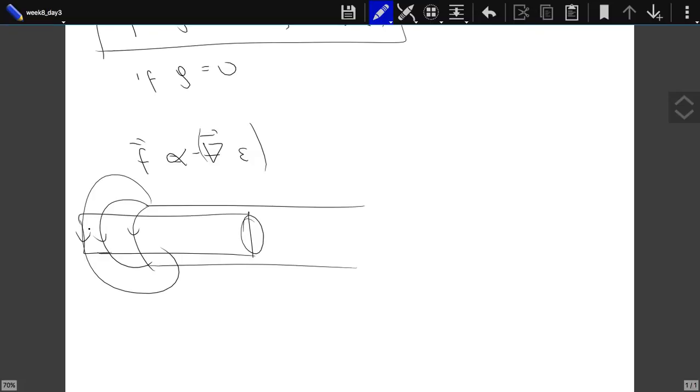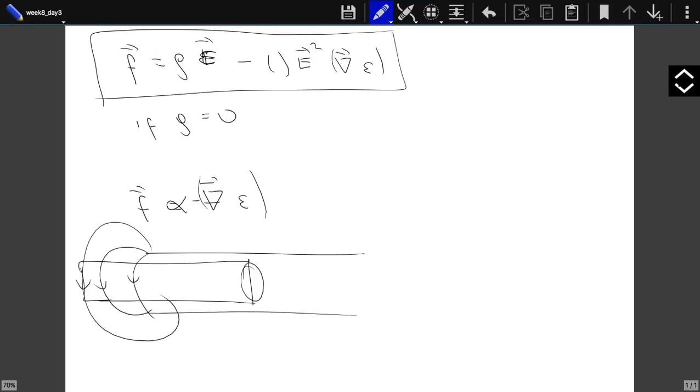But the derivation in your book, which seems to be also correct, tells me that it's in the region between these two dielectrics. That is the origin of it. Because, in fact, there are two sources. One, there is a force on that edge between these two dielectrics, and also in the region where these fringing effects are, because there also the gradient is non-zero.